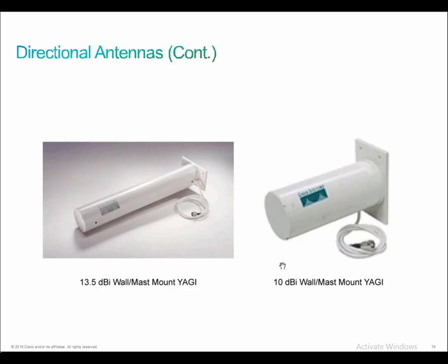Usually they'll have a designation on the antenna that'll indicate the polarity. See how this one on the left is mounted sideways, this one's mounted vertically, the logo might indicate that. I'm not suggesting that's the case here, but usually they'll have some sort of designation on there to identify how it's supposed to be mounted. If you physically mount it the wrong way, you're going to change the polarity of the signal, which means that the receiving antenna won't be able to receive the information.